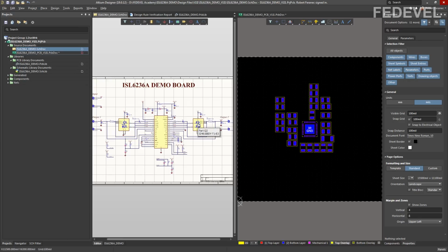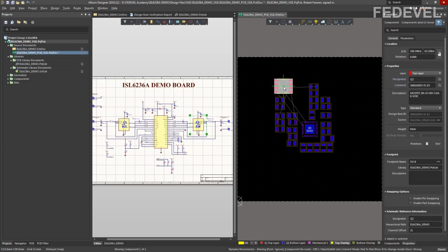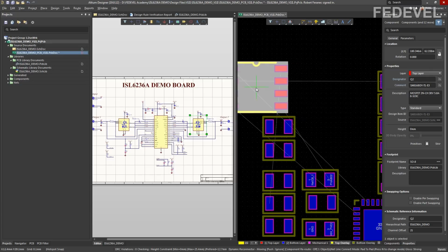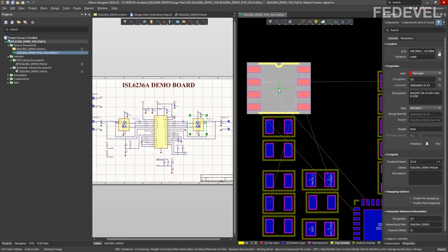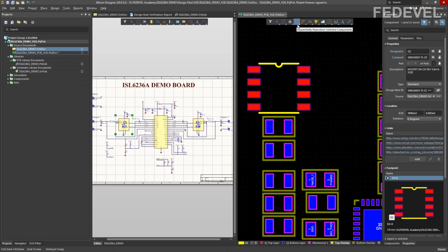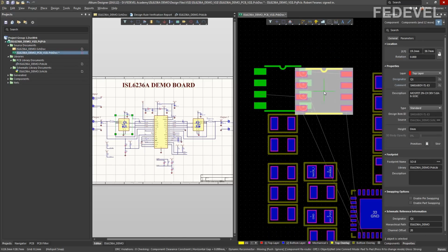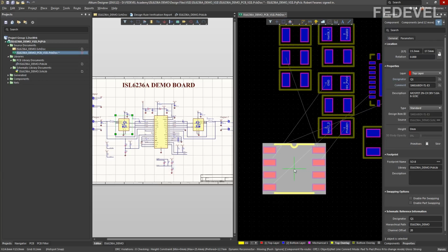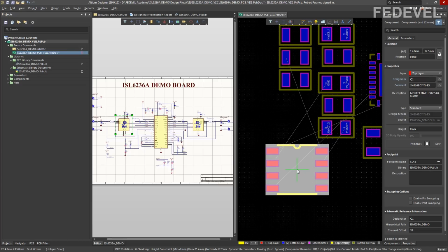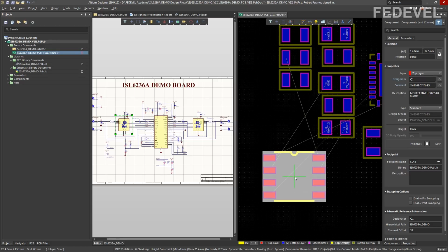First, left click on this transistor, reposition selected components, and place it into position 14.7, watch down here, okay? 14.7 by 39, left click, select this transistor, reposition selected components, and place this one down here at, again, watch the position, 14.7 by 15. Like this, left click.